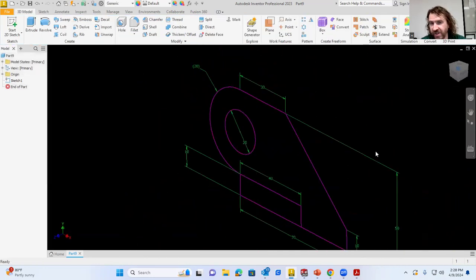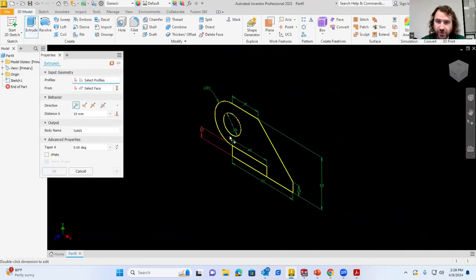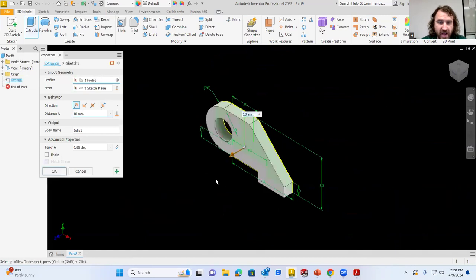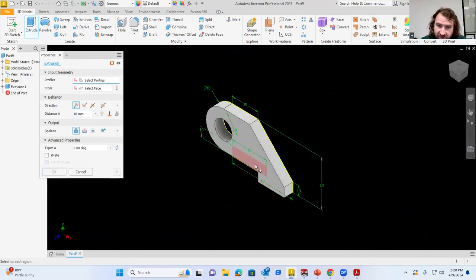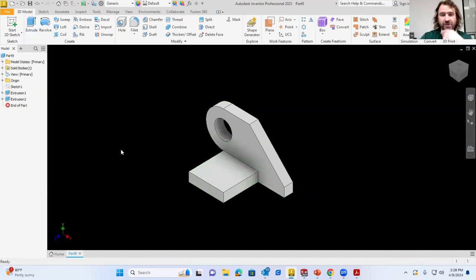We're going to extrude these. And our first extrusion is going to be the big one, the big guy here. This big guy is going to be an extrusion of 10 millimeters, super easy and done. And then we'll hit the plus sign. And then this small rectangle, this is where it gets kind of tricky. It gets kind of interesting because this is what's given to us in our right side view. We're given a dimension of 40, but we have to add this 10 that's to it already. So we got to 50. We'll hit enter on that. So here's our shelf, what we were talking about.